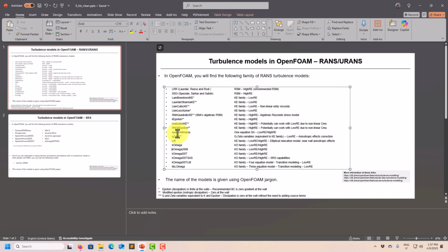Then you have, probably from a mathematical point of view, the most complete and most accurate model, which is the Reynolds stresses, or something in between the eddy viscosity hypothesis and Reynolds stresses, such as the V2F, the non-linear models or the algebraic models. So it's up to you to pick one, but just to stress, I prefer K omega 2006. If I move to the K epsilon family, I will choose the Launder-Sharma. It's a very good one, it's fantastic, I love it.